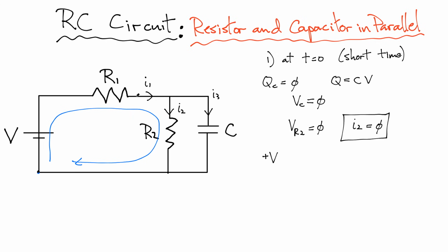As I cross a resistor in the same direction as the current, I get a voltage drop, and that voltage drop is given by Ohm's law, I1R1. And that's it. If I go down the center branch, I've just shown you that there is no voltage drop across R2, so we're done. Then we go back to where we started. We must get 0 if we finish where we started.